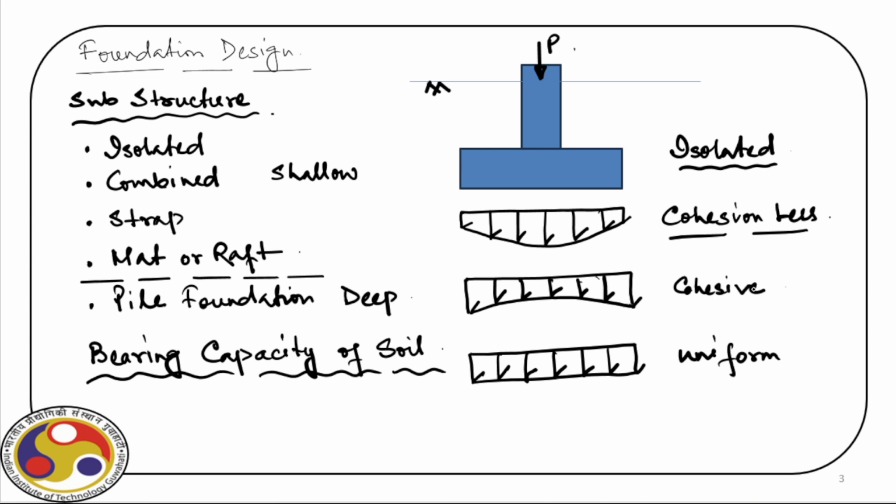Now the question to be answered is how to quantify the safe bearing capacity of the soil. So SBC. So SBC is based on the ultimate capacity of the soil that offers. Sometimes we actually quantify this as the allowable bearing pressure based on the tolerable settlement.